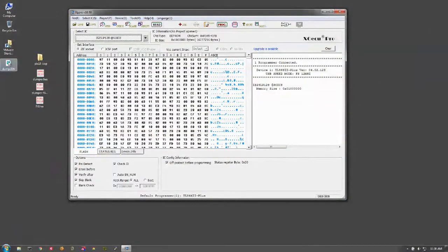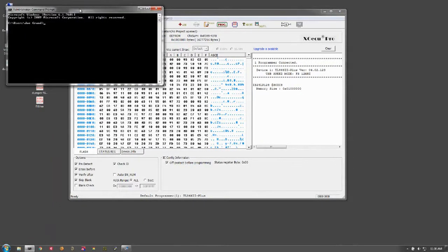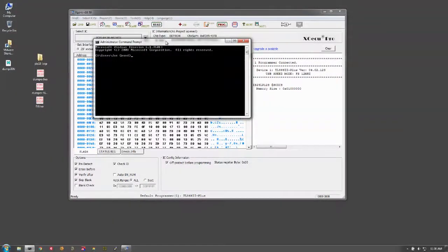Ghidra, the open source reverse engineering tool created thanks to the NSA, and other reverse engineering tools, dealing with RISC-V support. But what I like to do, if I extract some data from a device, the first thing I generally do is just run strings, which is a command that's going to show us printable ASCII. I'm going to set it to only look at printable ASCII characters in words greater than 6, because a lot of times regular non-ASCII bytes still look like printable ASCII, like you will see in the hex editor, there's like B.CZS. That's not really useful for us. We want to see things that are longer and potentially more useful.